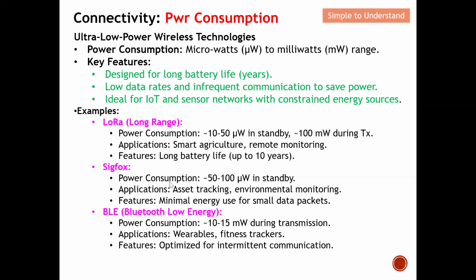The key applications for Sigfox will be asset tracking and some environment monitoring, for example temperature, humidity, etc. The key feature of Sigfox is minimum energy use for small data packets. Because Sigfox cannot send a lot of data, they don't use a lot of energy to transmit the data. Therefore they have this ultra low power.